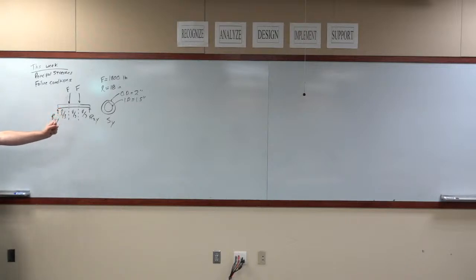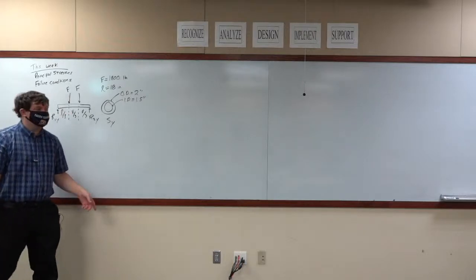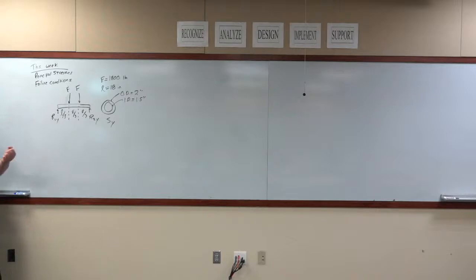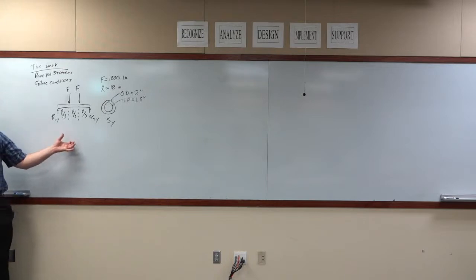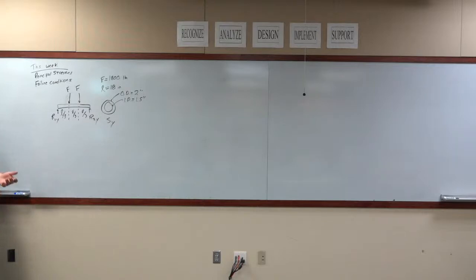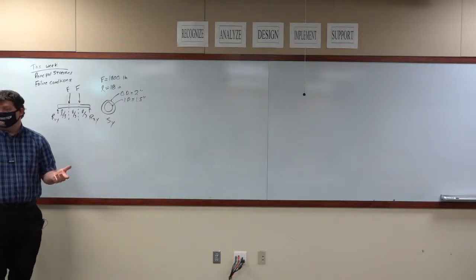If your axle bends, you've got problems. If it breaks, you have problems too. But since this is a metal structure that is ductile, if it even bends, it's not going to function properly. So bending, or here what we're going to call yielding, is a failure criterion for this. We do not want our axle to bend.